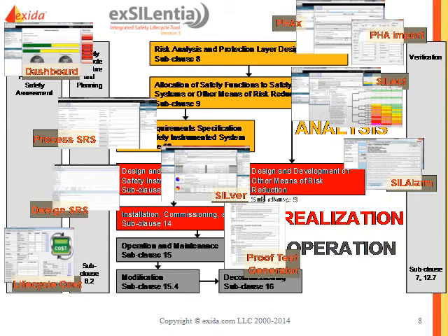I talked about other means of risk reduction. We have our SILalarm, our alarm rationalization software that you can use to help you prioritize the different alarms. There's a proof test generator that will help you to come up with proof tests for the safety instrumented function equipment items as they have been selected in the Silver tool. So based on the selections in the Silver tool, this proof test generator will come up with proof tests that you can implement to achieve a certain level of proof test coverage for the equipment in your safety function.